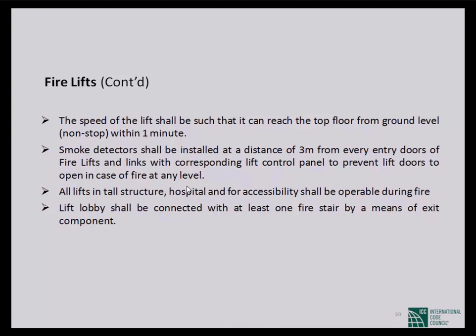All lifts in tall structures, hospitals or accessibility areas shall be operable during fire. The lift lobby shall be connected with at least one of the fire stairs by means of an exit component. So these are all about the fire lift. You have to be very careful about designing a fire lift, and not only about the design, you have to be careful about the operation at the time of fire, and it varies depending on the type of occupancy.